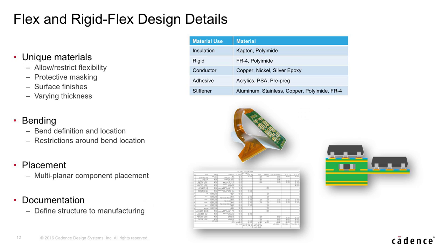And in driving those types of technologies, unique materials are used in the rigid flex environment as well. We see different types of polyamides, their thicknesses vary, types of platings, protective materials, different surface finishes, golds, tin, silver, and we see various thicknesses across these designs too, where you may have a rigid section that could be 8 layers that goes to a 2-layer flex and into a 4-layer rigid.